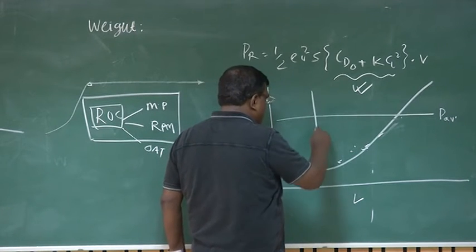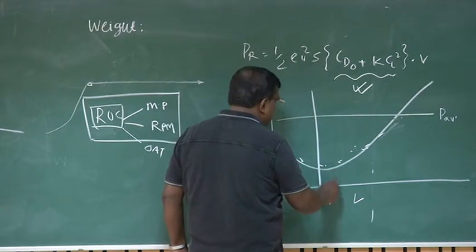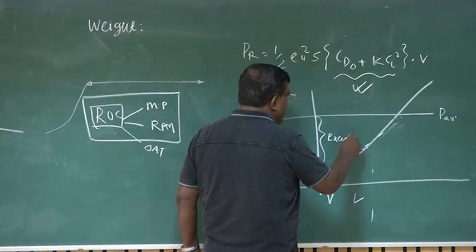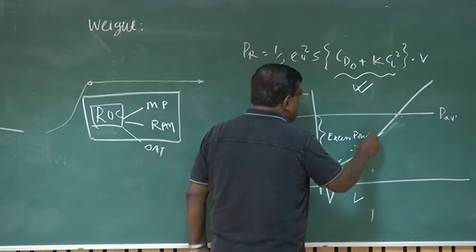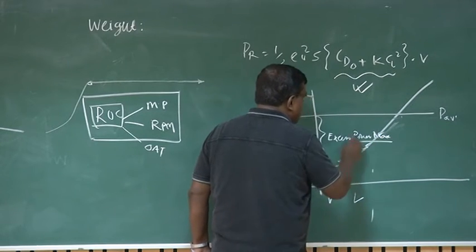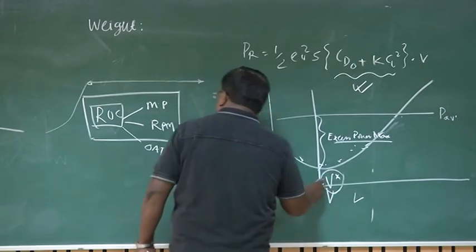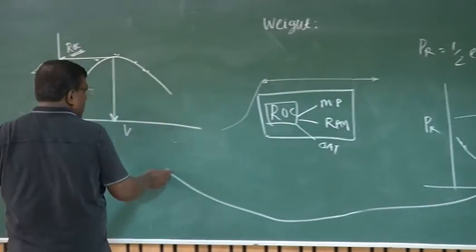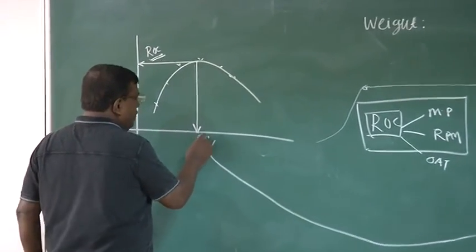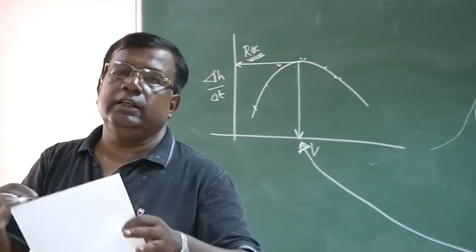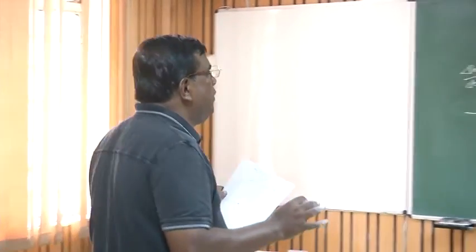And from here you find out the point V where excess power is maximum, and check that velocity V star, it should be equal to whatever you have measured through experiment. So then all this theory gets connected. Is this clear? How do you do the rate of climb experiment?